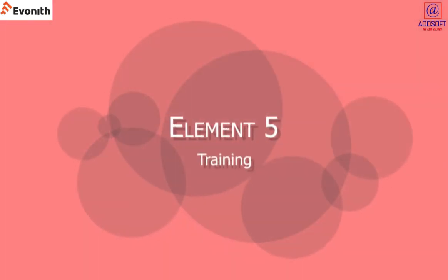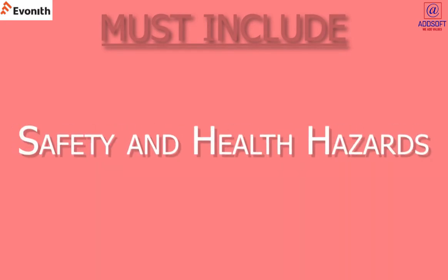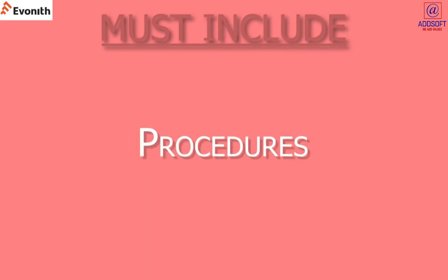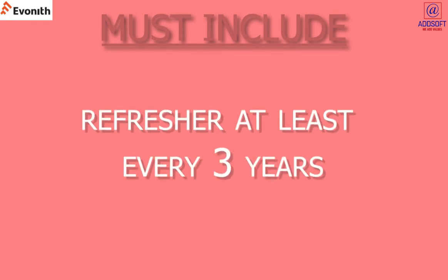Element 5. Training. Must include process overview, safety and health hazards, procedures emphasizing emergency, safe work practices. Initial training, refresher at least every 3 years.